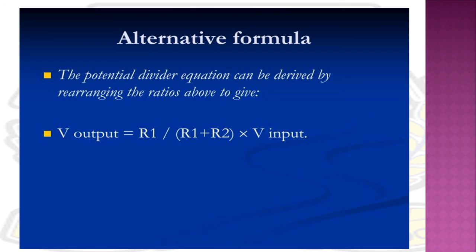Where the frequency response over a wide range is required, such as in an oscilloscope probe, a voltage divider may have capacitive elements added to compensate for load capacitance. In electric power transmission, a capacitive voltage divider is used for the measurement of high voltages.